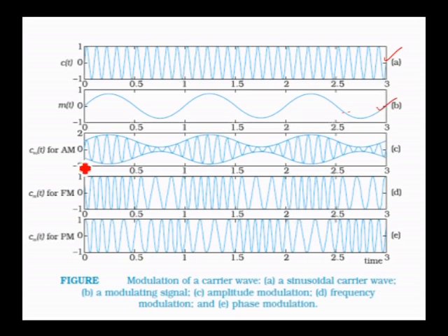So in the first picture here, you can see amplitude modulation is the process. For the high frequency signal, the frequency remains the same, the only thing is its amplitude is changing. As you can see, the amplitude is changing here, and in the second one, it is frequency modulation. In accordance with the instantaneous value of the message signal, the frequency of the carrier is modulated or changed. Similarly, you have the phase modulation here.